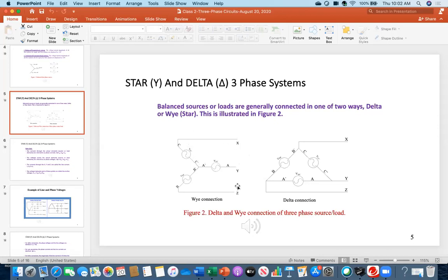Similarly, if you add a voltmeter between Y and Z, these two coils are involved. So in this case, the voltmeter reading will be different. If you connect a voltmeter between X and Y and get 120 volts, just as an example, versus if you connect a voltmeter between A and A prime only, you will get a lower or different voltage.